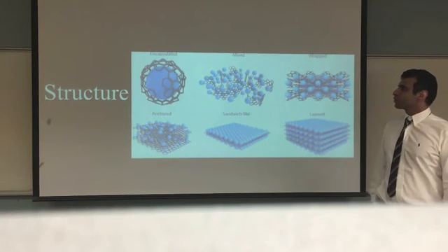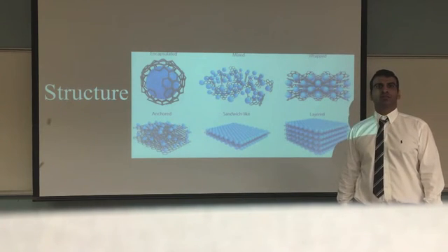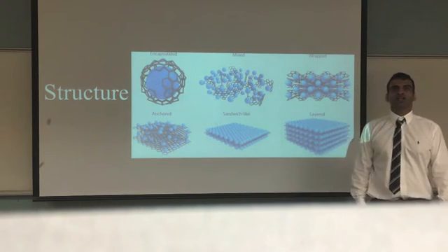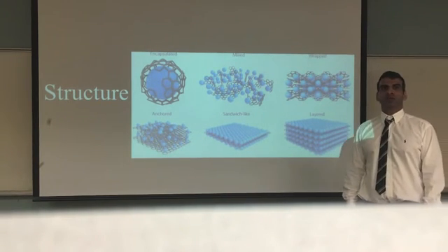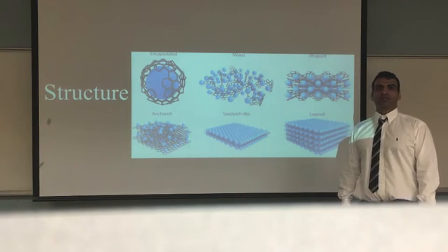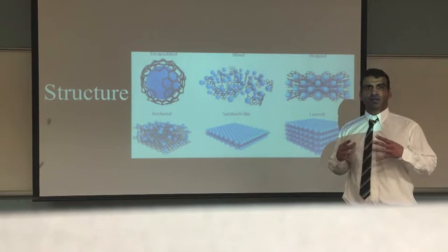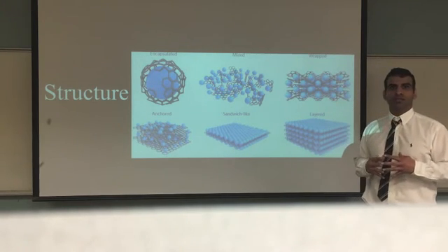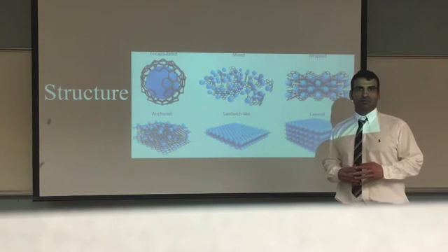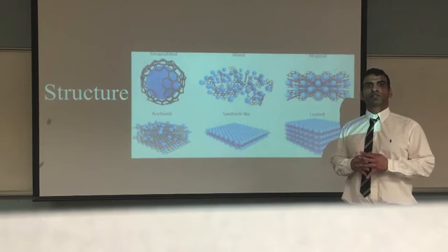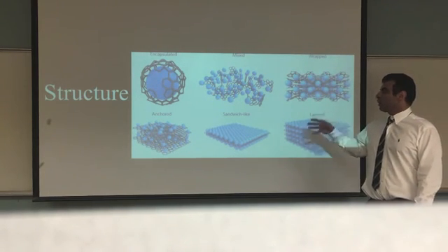Then we're going to cover the structure of the composites. The physical properties of composite materials are generally not isotropic in nature, but rather are typically anisotropic. For example, the stiffness of a composite panel will often depend upon the orientation of the applied forces and moments. Panel stiffness is also dependent on the design of the panel. The fiber reinforcement and matrix used to build the panels make the structure of the composites.